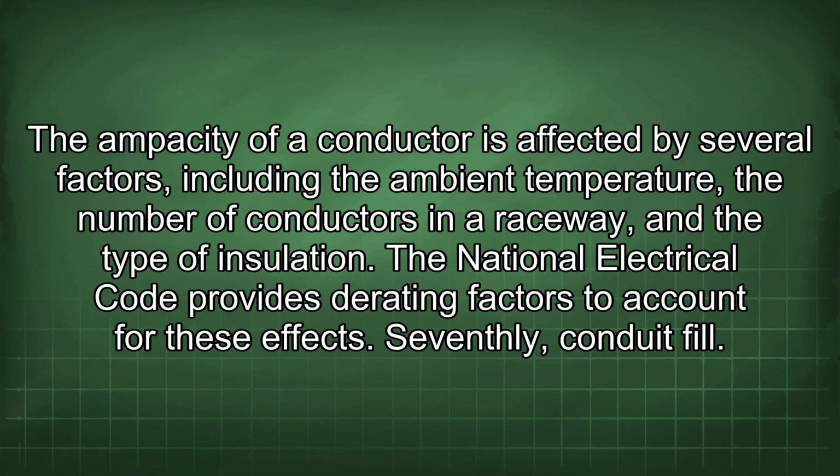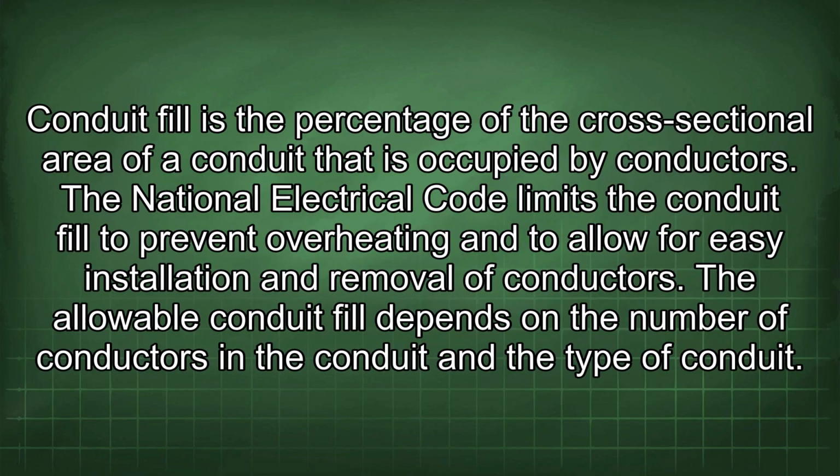Seventhly, conduit fill. Conduit fill is the percentage of the cross-sectional area of a conduit that is occupied by conductors. The National Electrical Code limits the conduit fill to prevent overheating and to allow for easy installation and removal of conductors. The allowable conduit fill depends on the number of conductors in the conduit and the type of conduit.